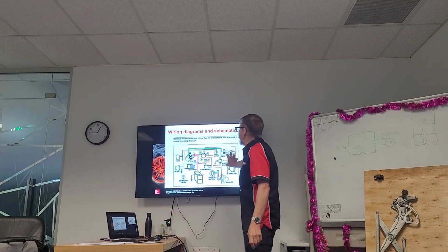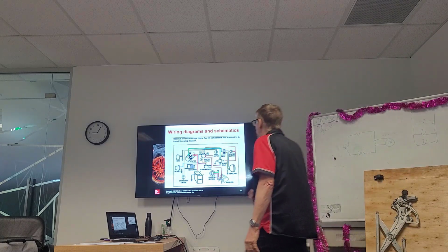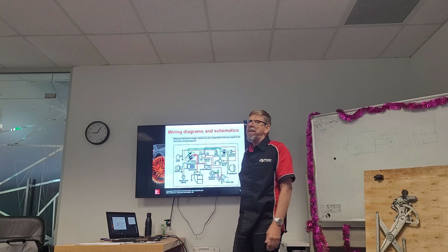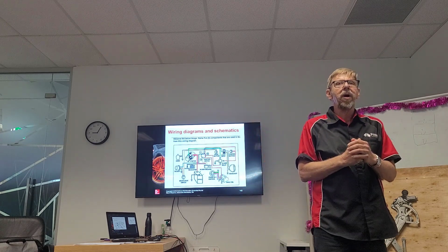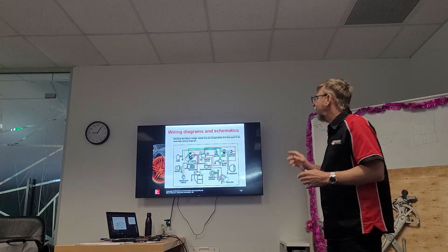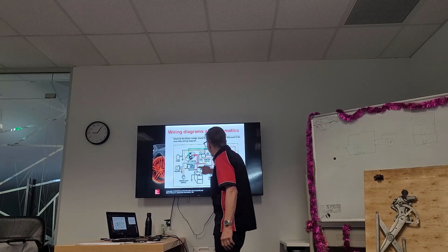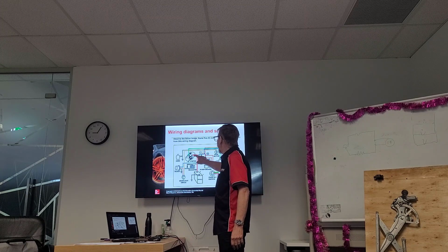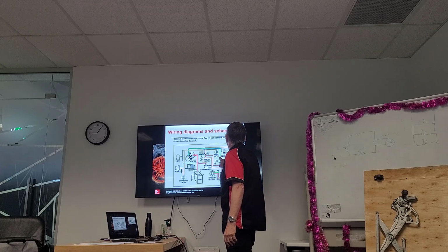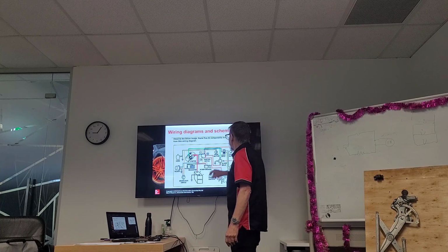If we look at this diagram, how many components are in there that run the starter motor? So here we have the starter motor. See the starter motor? Yes, sir. How can we discern what controls that starter motor from that wiring diagram? Switch. Well, we know there's going to be a switch, but we look at the diagram and work our way backwards. So there's our solenoid. There's our main battery power. See the positive battery power? Then we can come back from the solenoid. Where's it going to? Relay. It goes to a relay, okay? What controls that relay? That's what we're going to look at next.